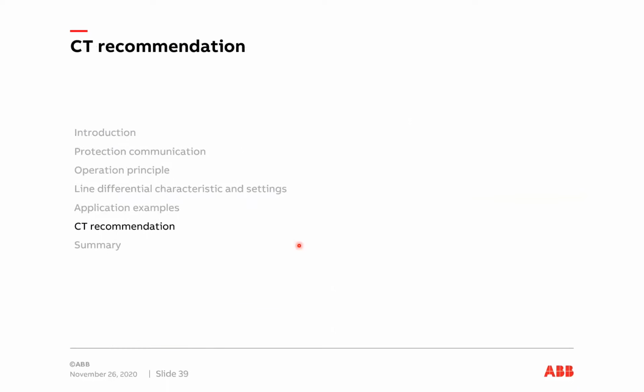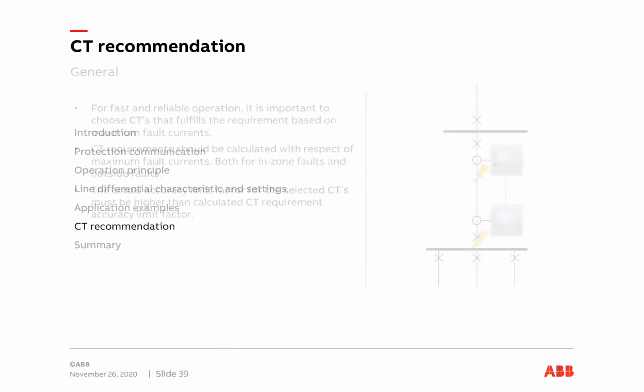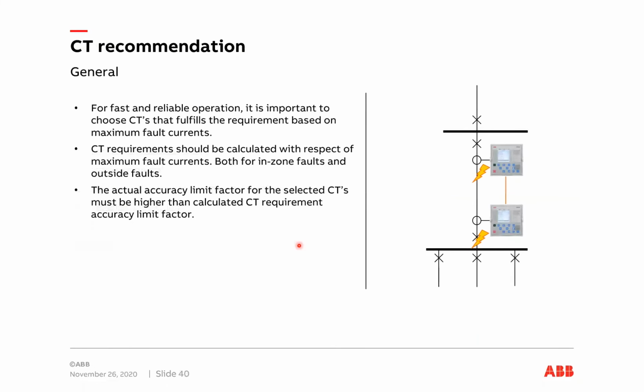Okay, then a couple of words about CT recommendation for line differential protection. So this is a very important part of the protection, because if you don't have proper CTs for the line differential protection, it might be that the CTs will saturate, and this will then result in a wrong operation, or that the operation will be delayed.